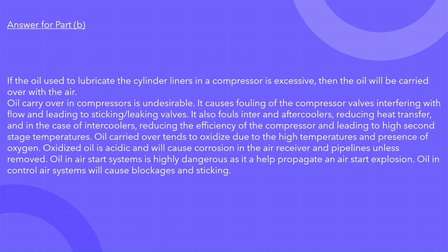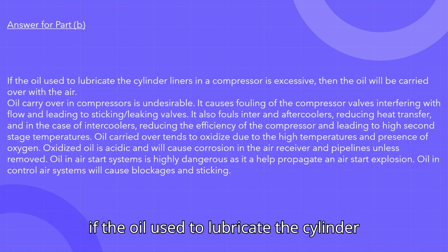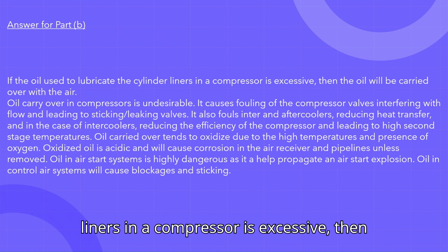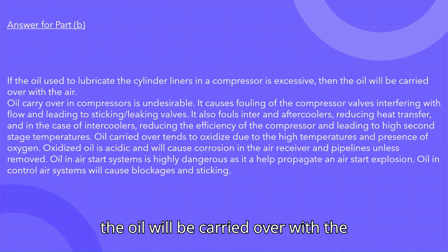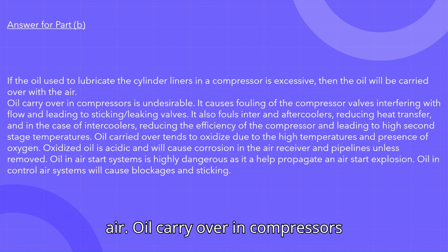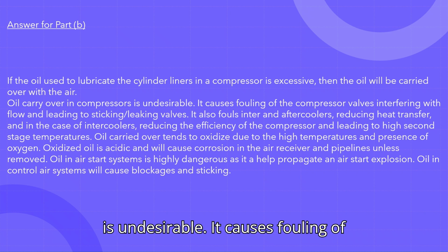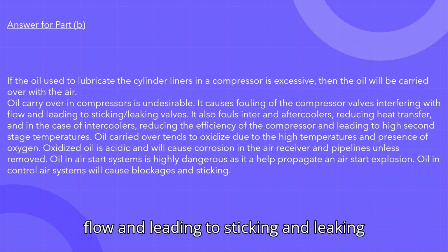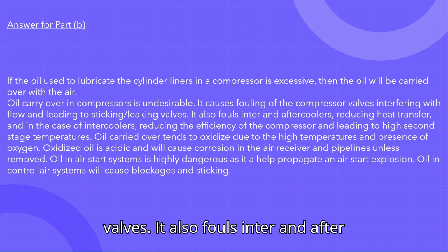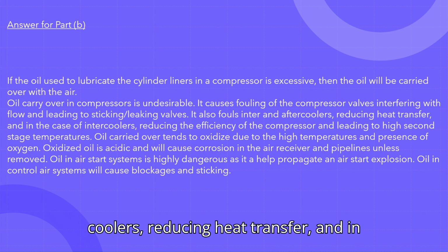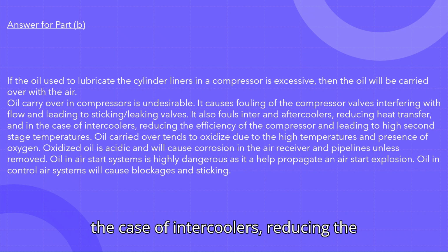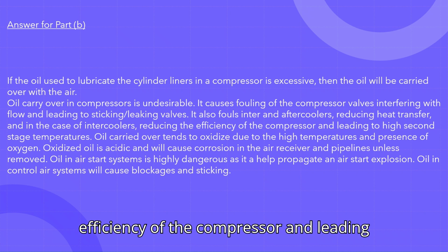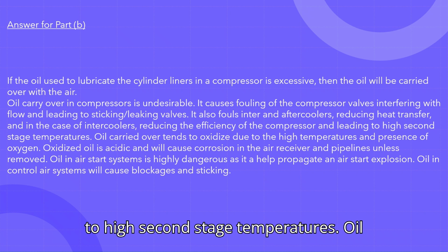For Part B, if the oil used to lubricate the cylinder liners in a compressor is excessive, then the oil will be carried over with the air. Oil carry-over in compressors is undesirable. It causes fouling of the compressor valves, interfering with flow and leading to sticking and leaking valves. It also fouls inter- and aftercoolers, reducing heat transfer, and in the case of intercoolers, reducing the efficiency of the compressor and leading to high second-stage temperatures.